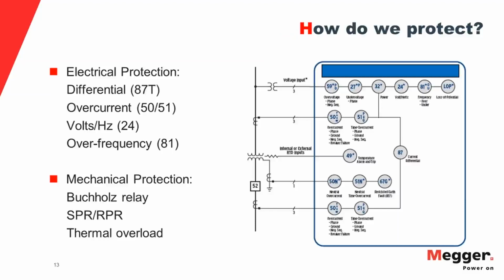You have overcurrent protection, which acts as a backup to differential a lot of times. Then volts per hertz. This is basically an abnormal condition, which is overfluxing of the transformer. You have overfrequency and underfrequency elements to address issues in the frequency if it goes beyond a set value.